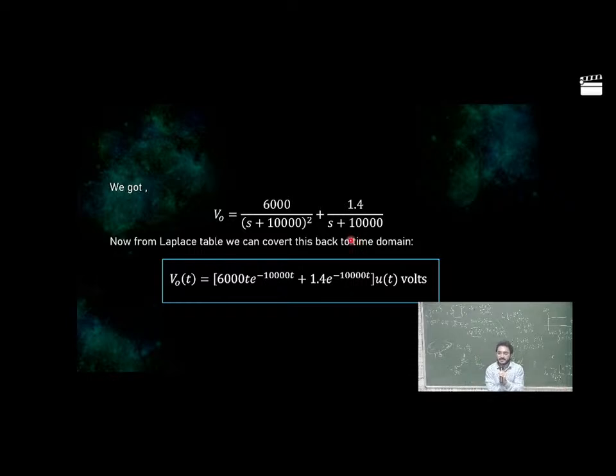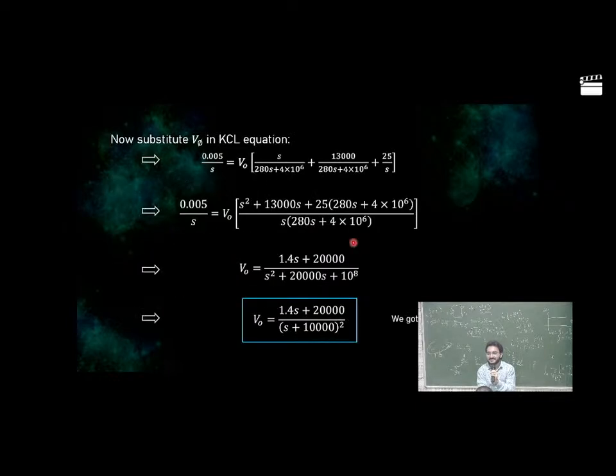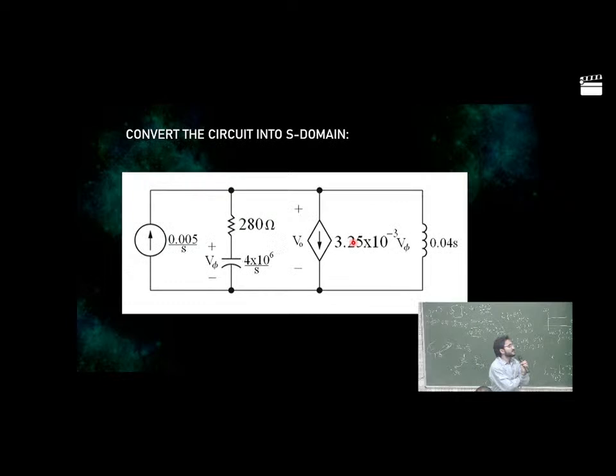Any further questions at last? Can you explain again what that rhombus was doing? Yes. This is actually a voltage dependent current source. Like you have a normal ideal current source, whose symbol is like this. This is a normal current source. Here, what is V5? V5 is the voltage across the capacitor.